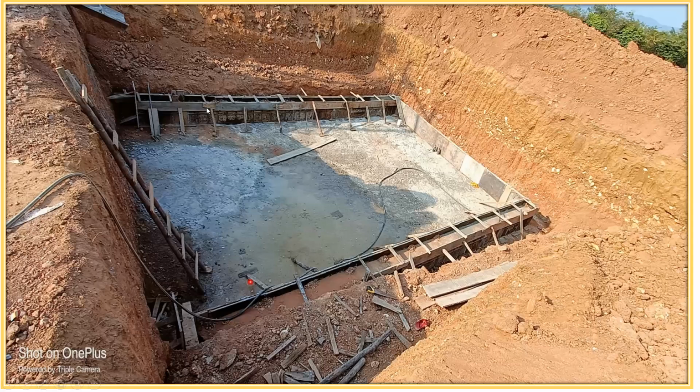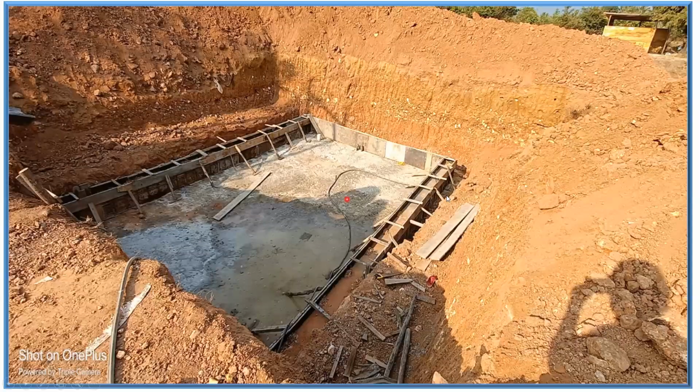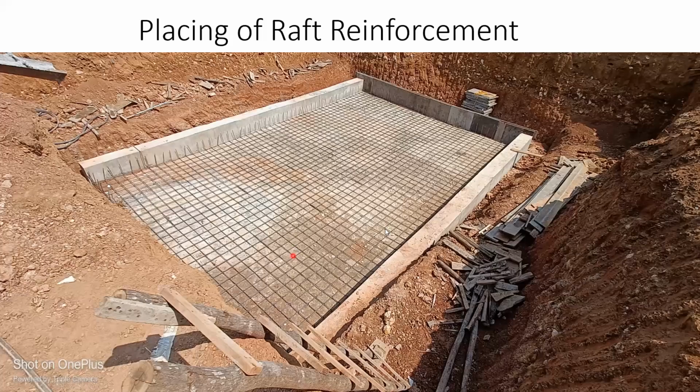You can see the concrete was poured in both walls, one on this side and one on the other side. After that we'll take it out, the de-shuttering will be done. You can see how the concreting was done. After that the de-shuttering will be done, and then the curing process is going to start. Once this is done, next we are supposed to put the foundation here. So we went with a raft foundation.